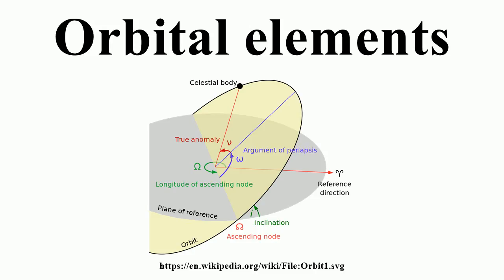Orbit prediction. Under ideal conditions of a perfectly spherical central body and zero perturbations, all orbital elements except the mean anomaly are constants. The mean anomaly changes linearly with time, scaled by the mean motion. Hence, if at any instant the orbital parameters are known, then the elements at a later time are given by this relation. Perturbations and elemental variance. Unperturbed, two-body, Newtonian orbits are always conic sections, so the Keplerian elements define an ellipse, parabola, or hyperbola.